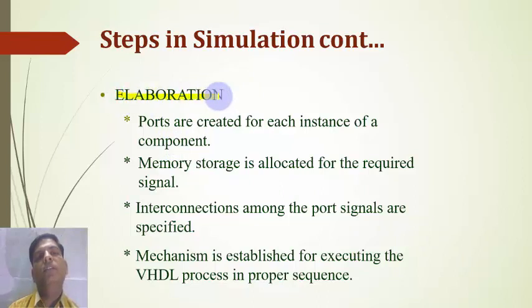Next, elaboration. The ports are created for each instance of a component. Memory storage is allocated for the required signals. Interconnections among the port signals are specified. A mechanism is established for executing the VHDL processes in proper sequence.